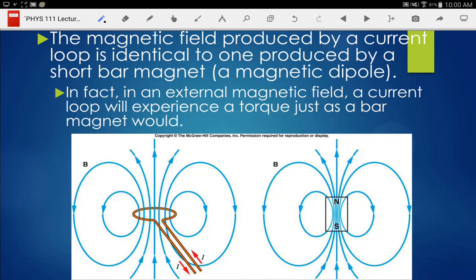Well, yeah. That explains essentially how we were able to make our electric motors work. Because we had loops, coils, we had current going through those coils, and that current then was making a magnetic field, so it was like we had a magnet that was able to rotate and a permanent magnet, and so the magnet would have a torque to make it align. And then what did we do when we had them aligned? We turned it off. For our homemade ones, we just turned it off. And so it's rotating, it gets here, and then it turns off, and so it freewheels for a half cycle, and then we turn it back on, and it pulls it around again.